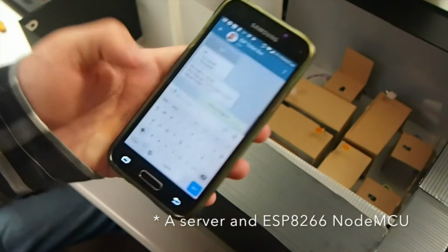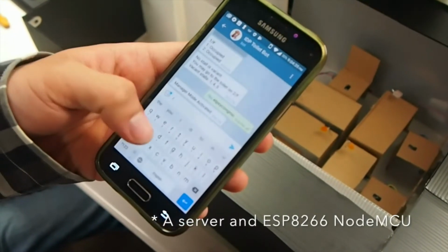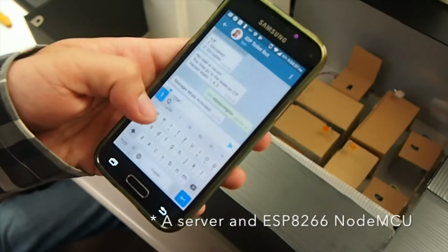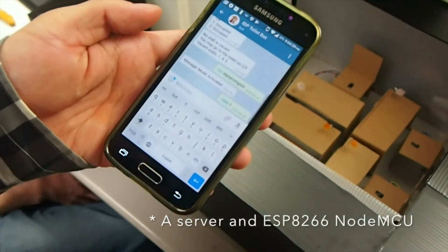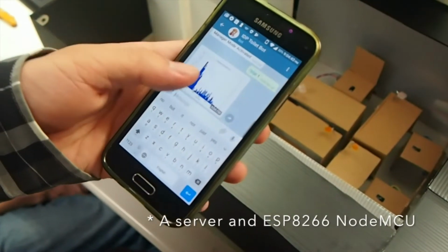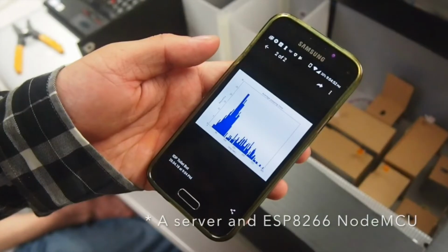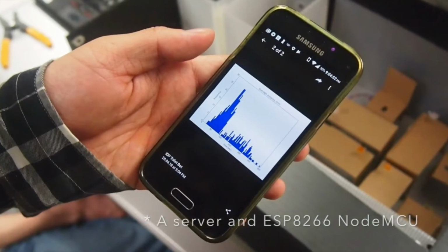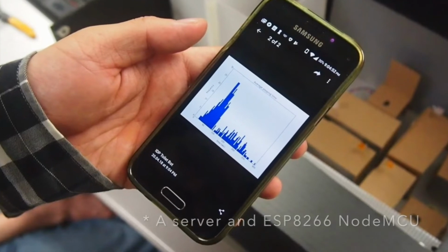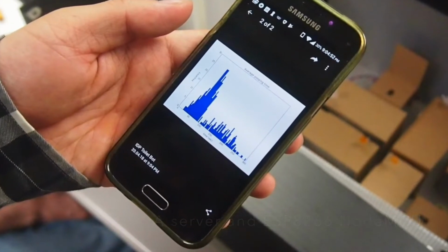The reason why we use a bot API by Telegram is that it has cross-platform compatibility, as Apple and Android phones can use the same plugin. The ESP8266 NodeMCU connects with the Arduino Mega and LCD monitor in the smart toilet system, and the PCB in the smart cubicle system, and collects information including occupation of toilet stalls and cubicles.